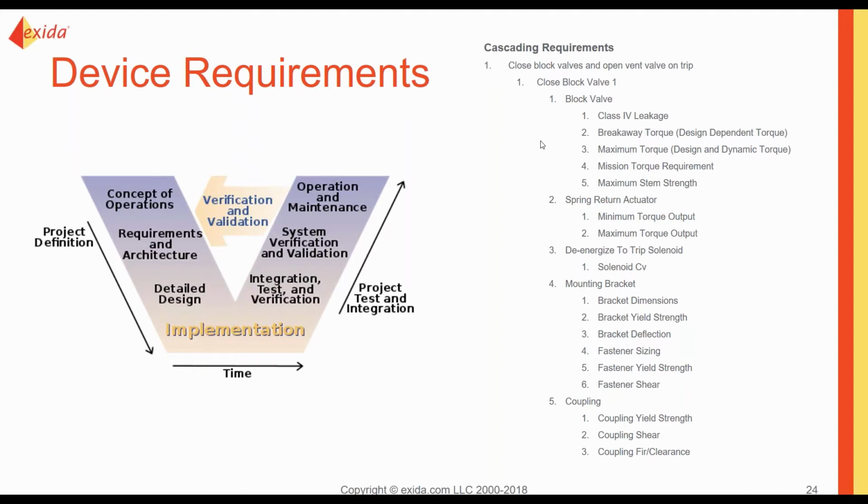So even just properly sizing that actuator to the valve doesn't happen all the time. I think what happens is a lot of times people will over design the actuator because they're concerned about increases in torque over the mission of that valve, but if you put too large of an actuator on it and the stops aren't set, you're going to shear that valve stem.